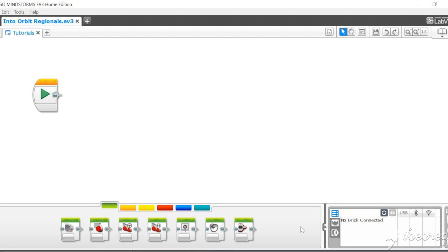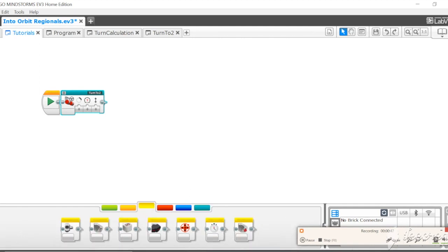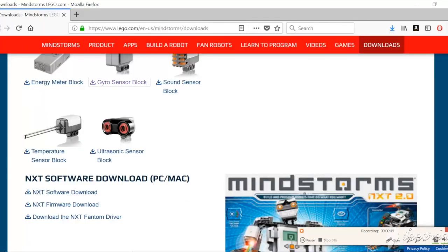Some ways to avoid drift is to make sure the robot is still when turning it on, and you don't use any rapid movements of the robot. Both of these can easily cause drift. The most common way to remove drift, which is what most people use, is to unplug it and plug it back in again. This can be difficult because if the gyro moves at all during this process, the drift will continue. So we have made a short program that helps to deal with this, but it isn't usable in every circumstance.